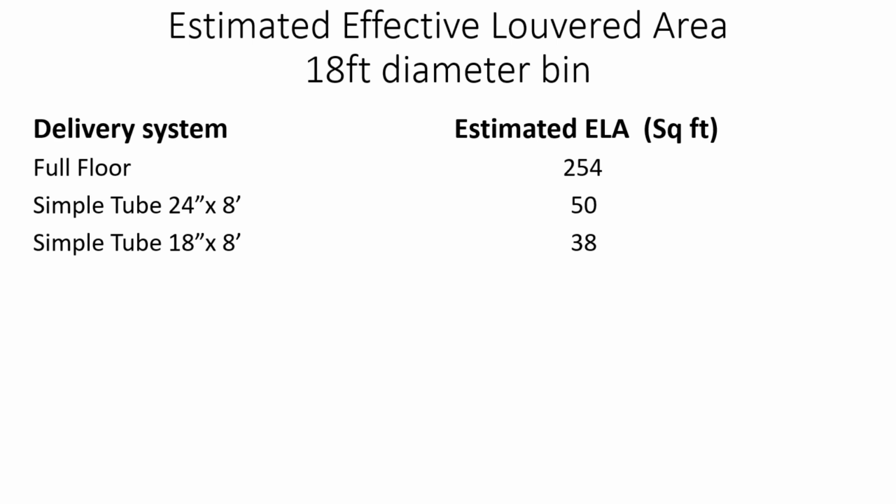In many instances, you'll be thinking that you're going to get significant additional airflow, but if you have too low of square footage, no matter how big the fan you put on, your airflow will be restricted, and in many instances, you'll just burn up the electricity that you're using to run your fan in friction.